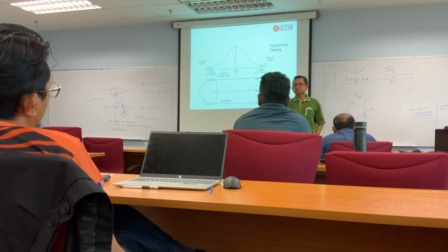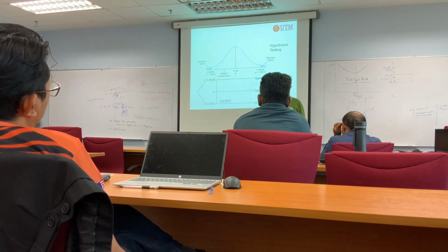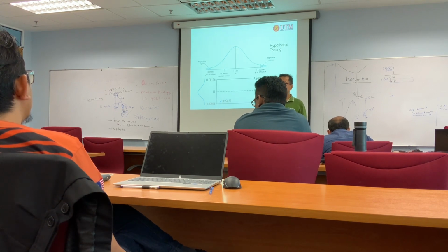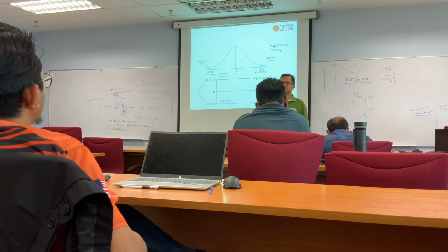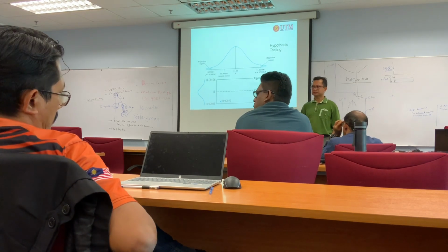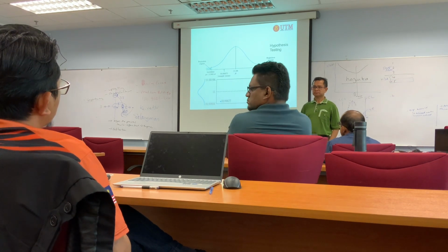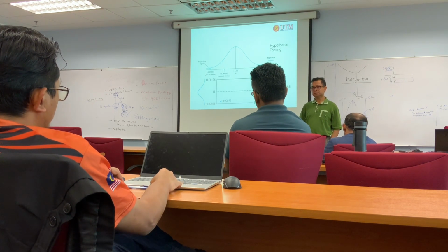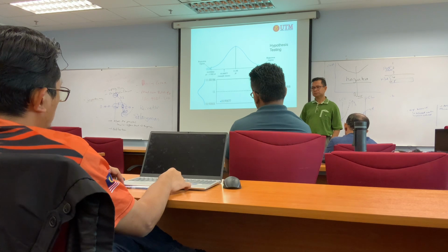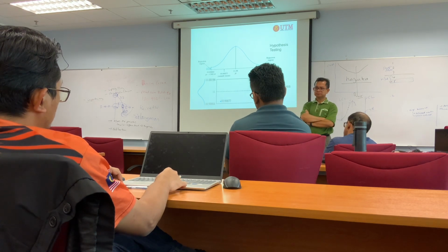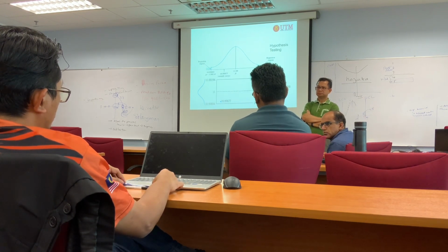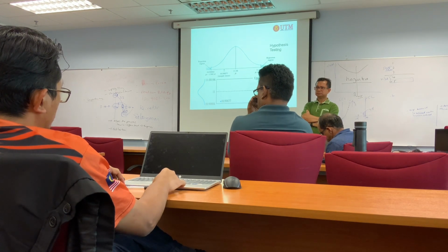Because last time when I was in the concrete industry, I was one of the QC. I monitored the quality of the concrete. We have 1 day, 3 days, 7 days, 28 days curing. I don't know about the 6 month data and so on, but I just plotted this graph. So during that time I was thinking, for example, grade 30, 30N is 30 normal, right? That should be the strength at 28 days, which is 30. So the 30 is the middle, right?